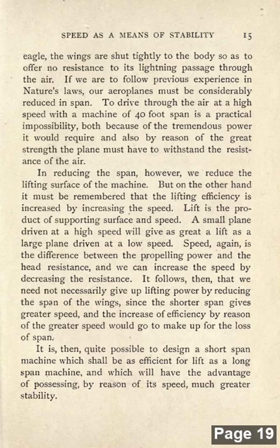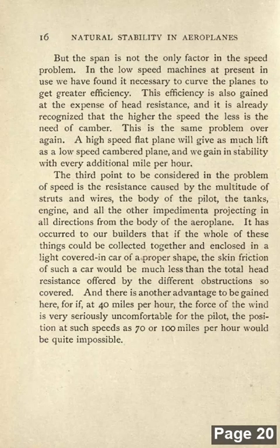It is, then, quite possible to design a short span machine which shall be as sufficient for lift as a long span machine, and which will have the advantage of possessing, by reason of its speed, much greater stability. But the span is not the only factor in the speed problem. In the low-speed machines at present in use we have found it necessary to curve the planes to get greater efficiency. This efficiency is also gained at the expense of head resistance, and it is already recognized that the higher the speed the less is the need of camber. This is the same problem over again. A high-speed flat plane will give as much lift as a low-speed cambered plane, and we gain stability with every additional mile per hour.